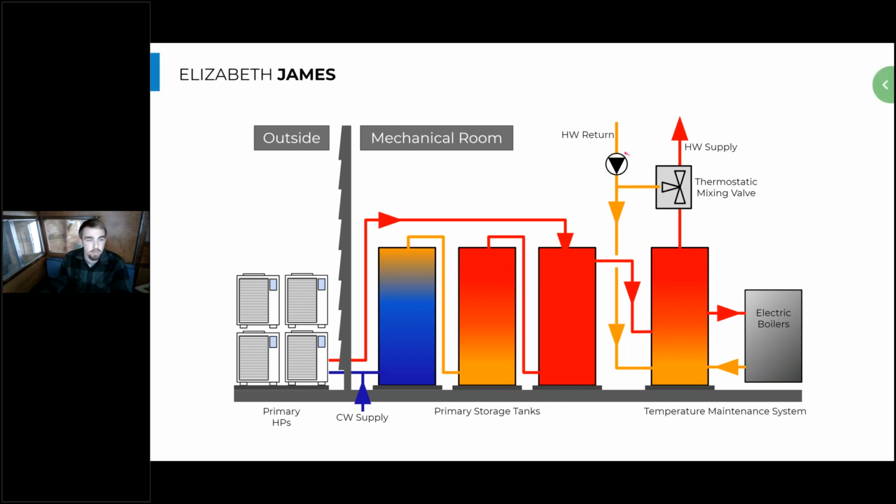But they don't actually have to make up for the entire heat loss in this circulation loop, because you'll see as soon as hot water is sent out to the building, we have this makeup water coming in to serve the building. And so this is 150-degree stored water that the heat pumps have heated really efficiently, and it's making its way through this tank before it goes out to the building to be used. So as it makes its way through this tank that is accommodating the warm recirc water, it's actually passing through and heating up that coolish, warmish water as it passes through.